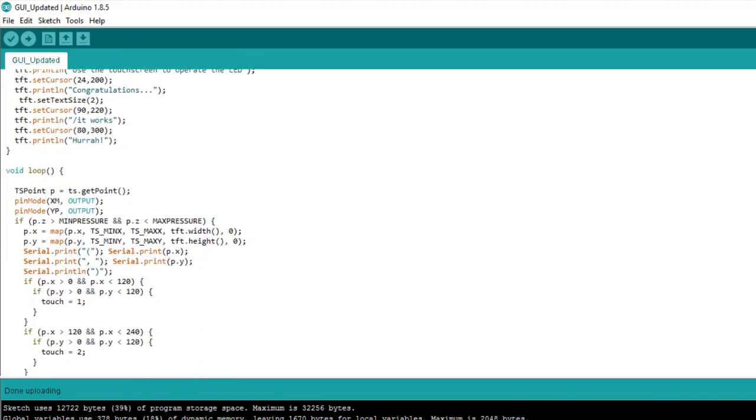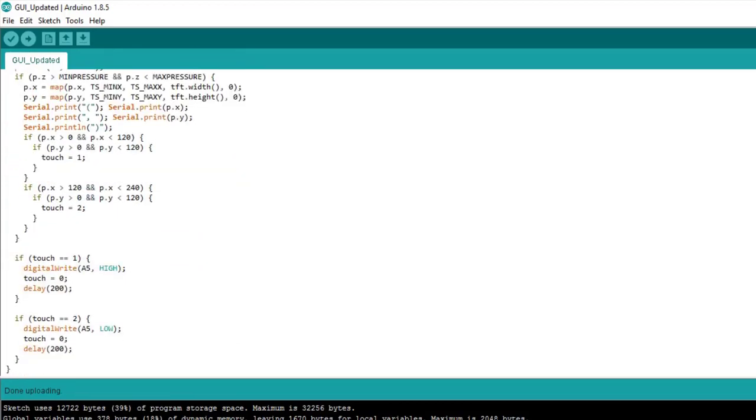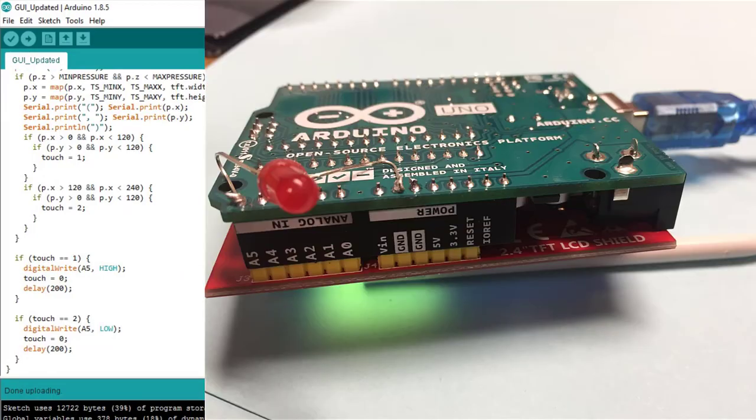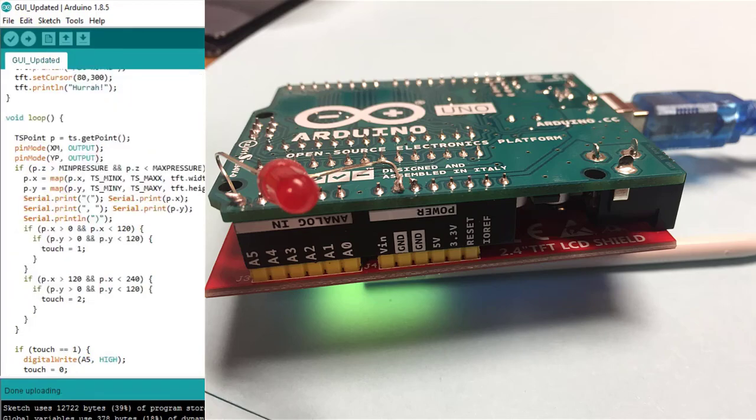And then the coding is pretty simple if you just go through it. Because of the Arduino that we are using, there's only one pin that's available, which is A5. We are going to connect our LED to A5. If you wish to connect it to a resistor, which I would really recommend, I didn't do it, but I really recommend you adding a resistor to your LED, and then it should work. So let's make sure you make all those changes that I mentioned.